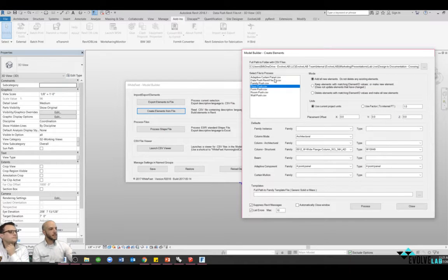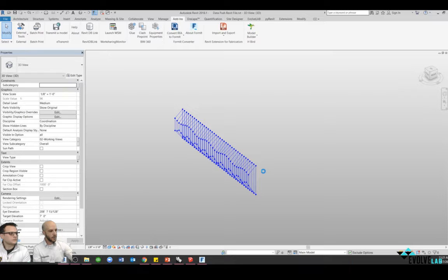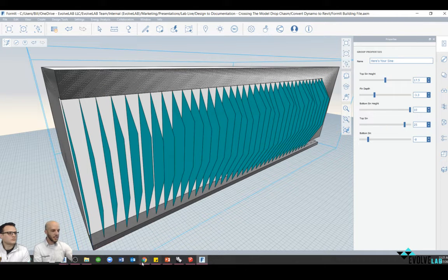Okay. All right, so with this process, I was testing a little bit before, so that's what we're seeing. In here we have this floor push. That was from when I was building it from Grasshopper. It's populated it in here based on my folder location and the file location. And so I could click process this. What it's going to do is start building those floors in Revit. Let's see. Interesting. It's actually building the curtain wall.